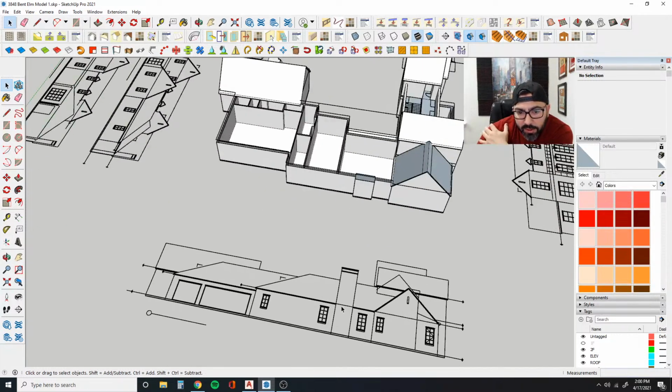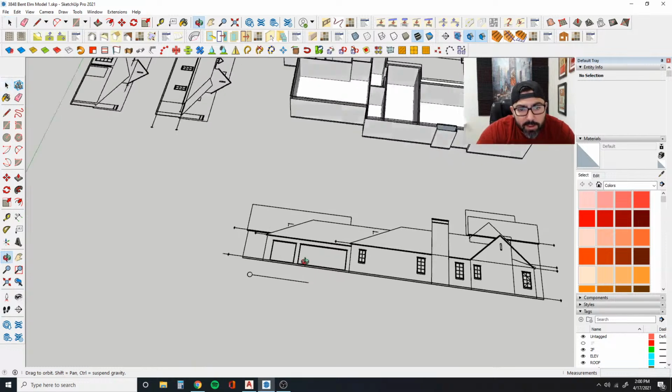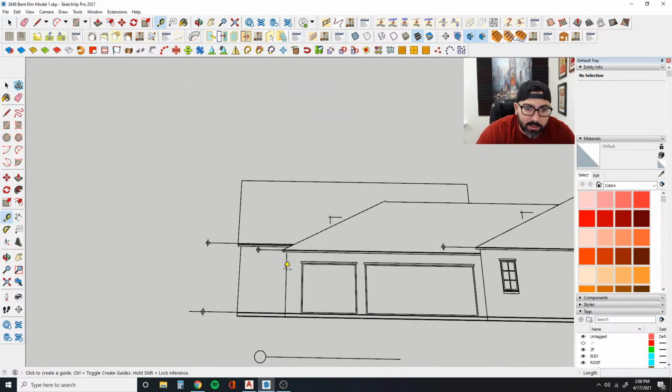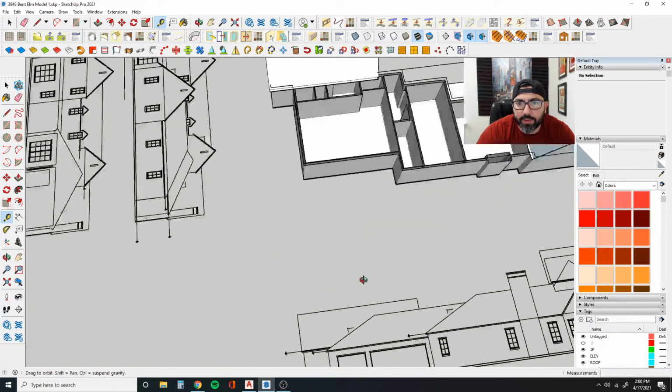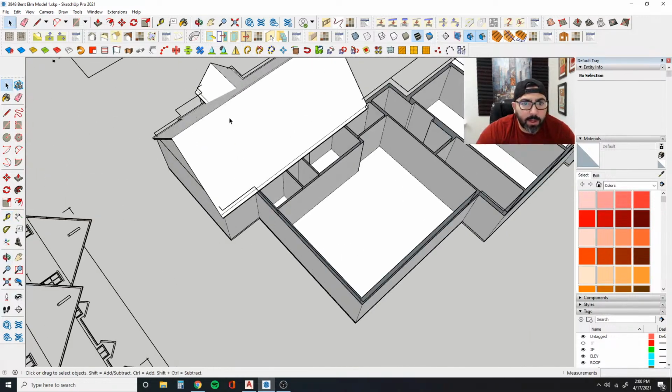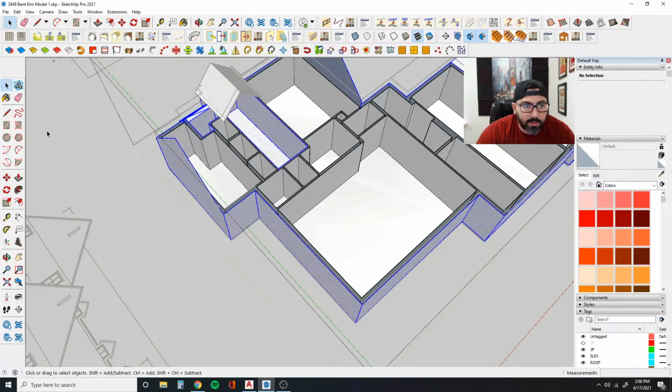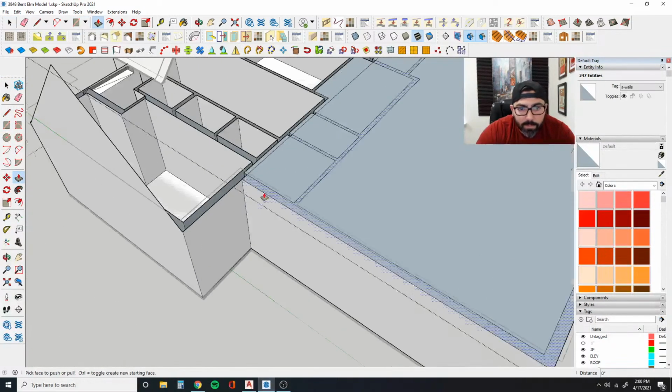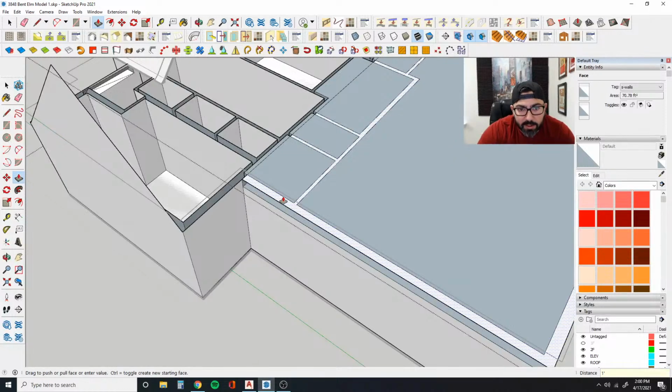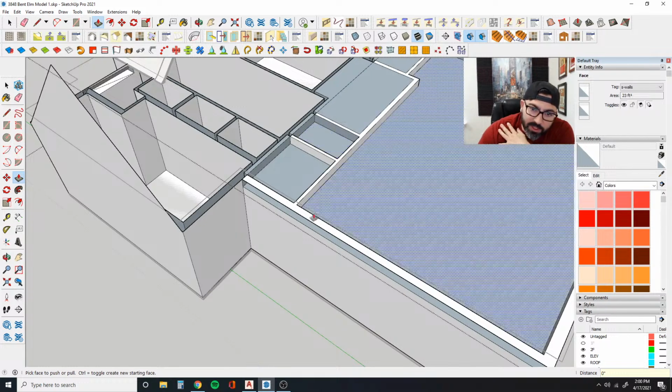And let's see, so I think I have 11-foot ceilings here, and then the garage is dropping down to 10 foot, so we have a 1-foot drop. So the way I'm going to do that, I'm going to go ahead and break these lines, and this whole area is going to come down a foot. And if you didn't know, I just hit 1 foot, right?